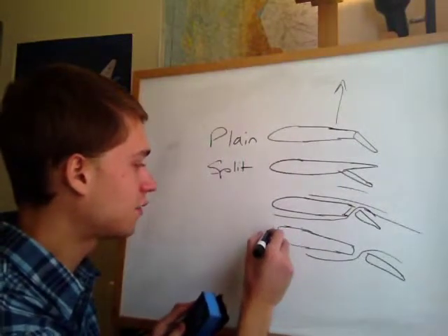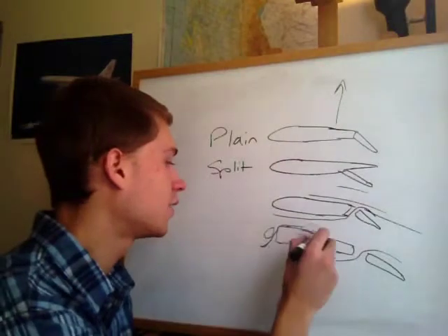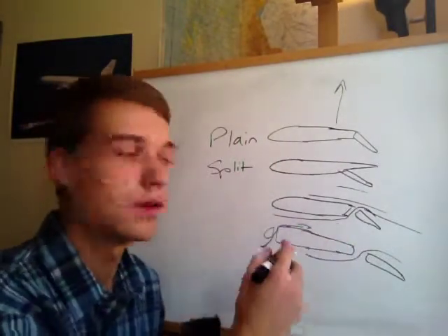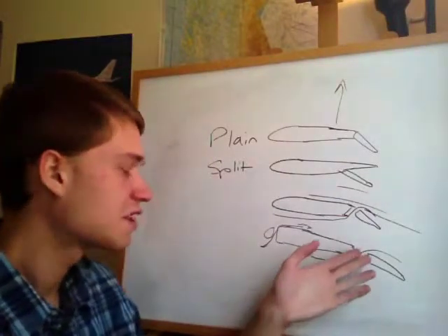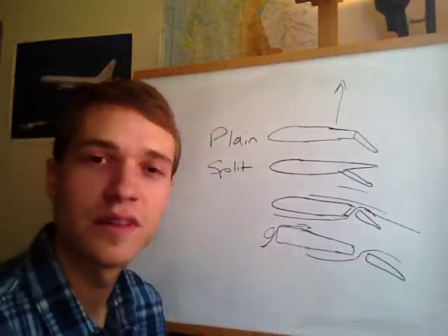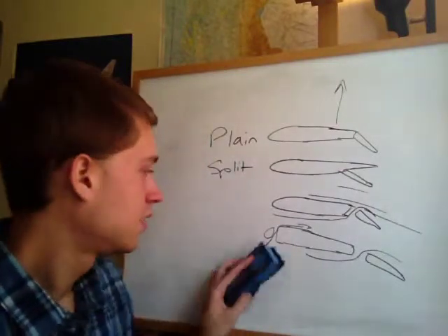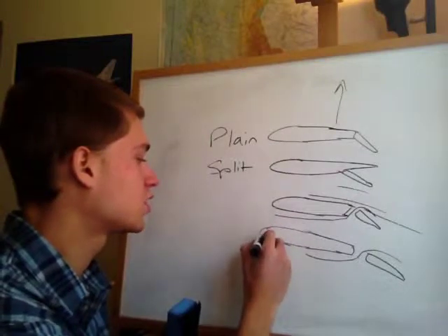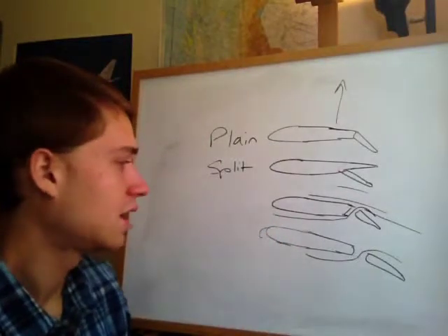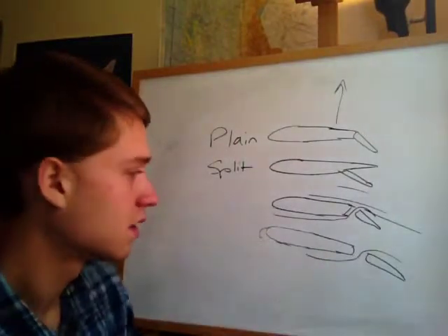Yeah, you might have a slot on the front of the wing that opens up when you're going at lower airspeeds, and that helps the air accelerate from the bottom over to the top. Kind of similar to this, but we really don't fly those kinds of airplanes when we're training. But just so you know about that, there's also leading edge flaps where this will extend out like that, and that also helps produce more lift at slower airspeeds.